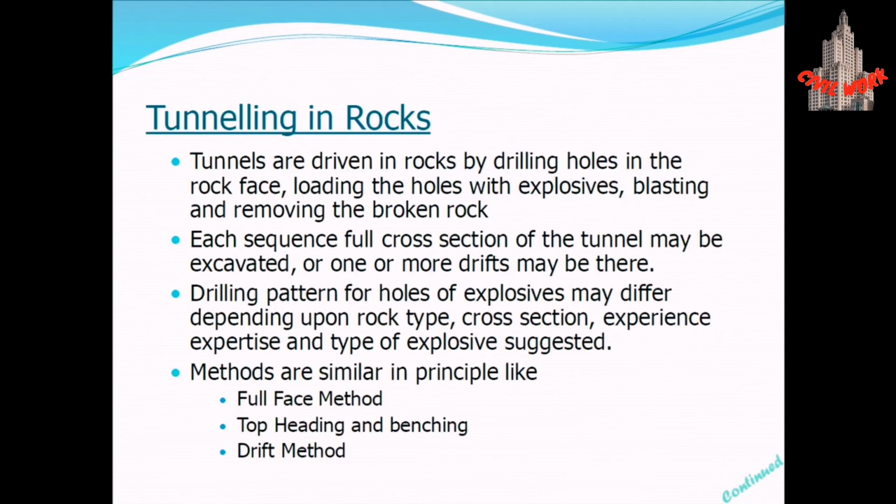Tunneling in rocks. Tunnels are driven in rock by drilling holes in the rock face, loading the holes with explosives, blasting and removing the broken rock.